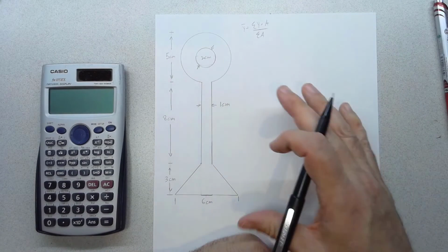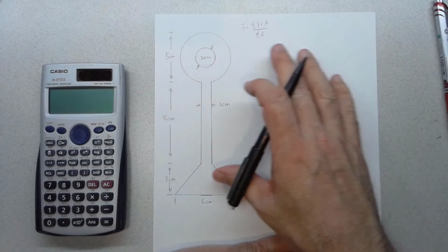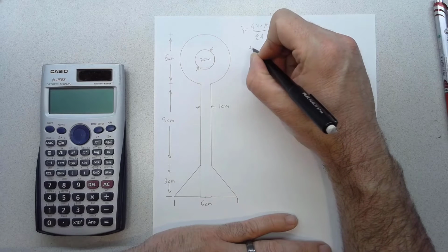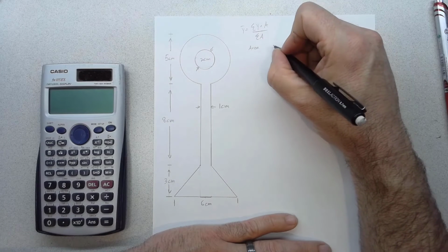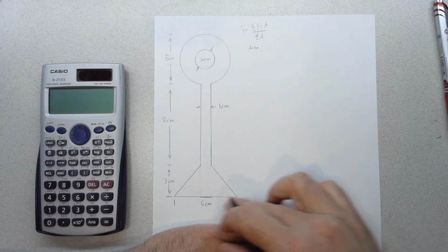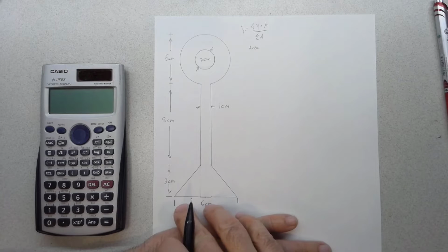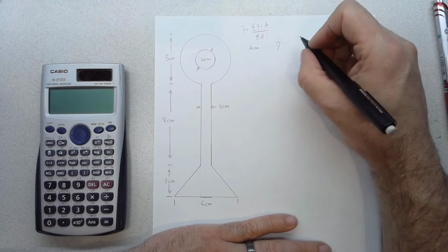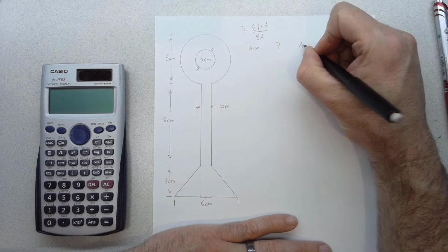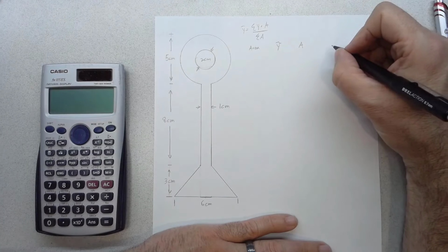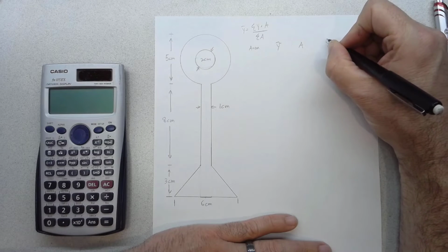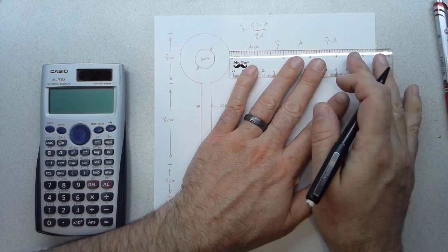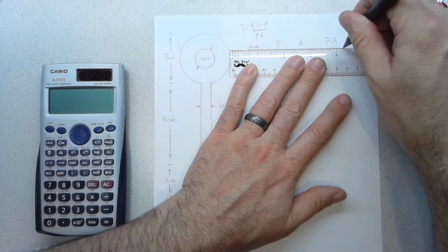And so if we have a complicated shape like this, we'll typically set up a table format to find y bar. So I'll say first column will be the name of the area. Second will be the distance from the bottom. I always use the lower edge of the section as my reference point. So that's going to be the individual y bars. And then we'll have the area of each area. And then we multiply those together to get the last column, the individual y times area. Okay. So set this up in a table.